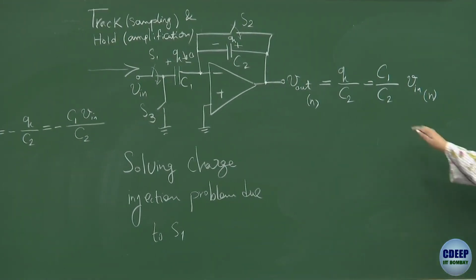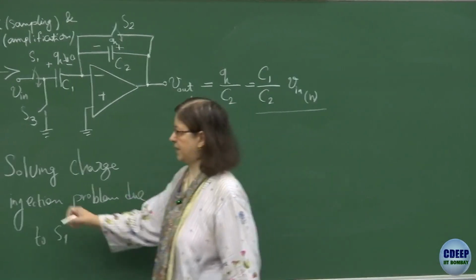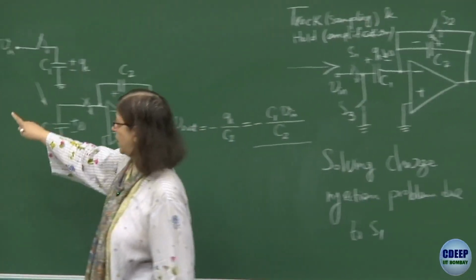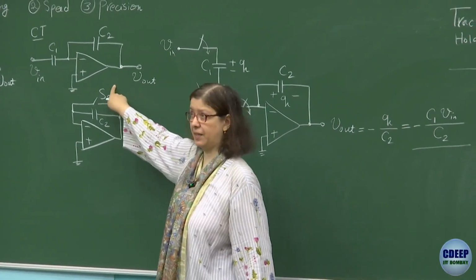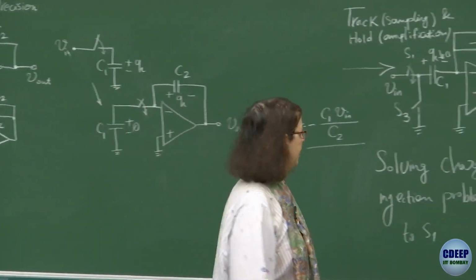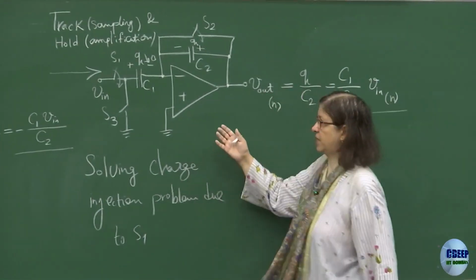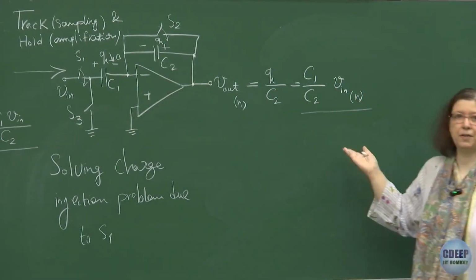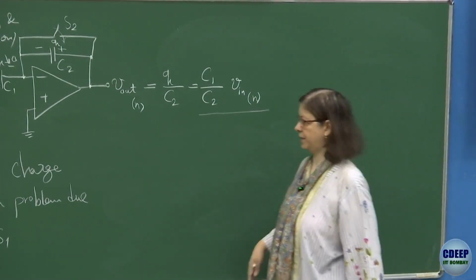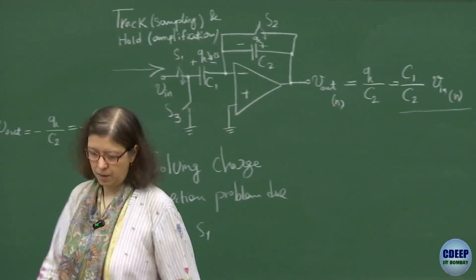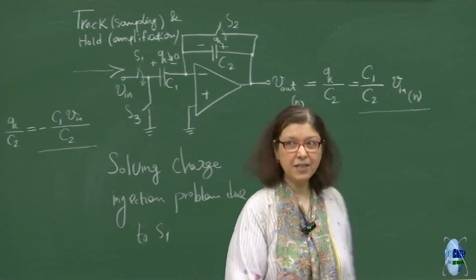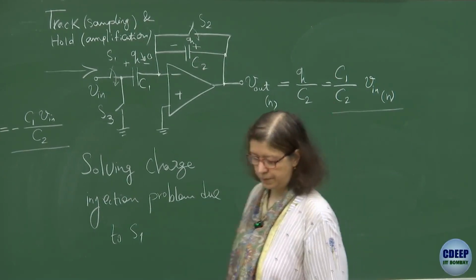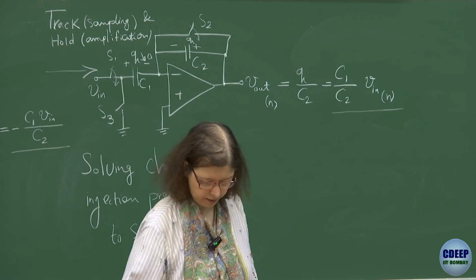This is non-inverting. This is inverting. That's another difference. That's very interesting. Even though the initial analog version was also done as an inverting amplifier, by this method, where we are changing the polarity of the charge transferred to C2, we can make a non-inverting amplifier. That is the next difference. So the non-idealities are the same as before. Therefore, switch sequence matters a lot.